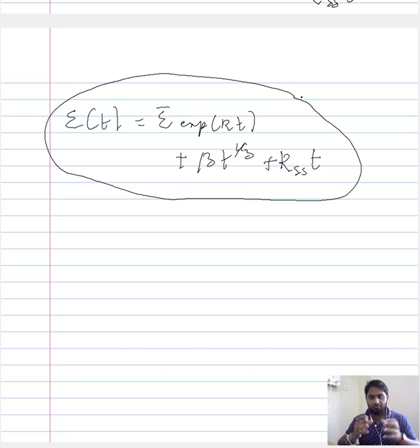So far, we have considered only sections of the creep curve. We have sectioned the creep curve based on its slope or the strain rate, studied each individually, and found the material property or behavior that is responsible for each of these sections. But now we saw that Andrade was able to arrive at an overall expression that can give you the amount of strain in any period of time. You can substitute any time here, and then you would be able to calculate the overall strain.